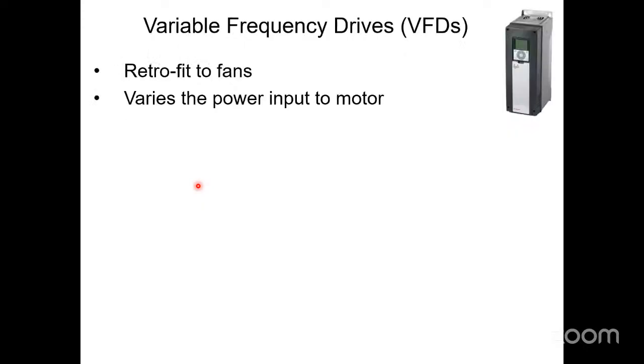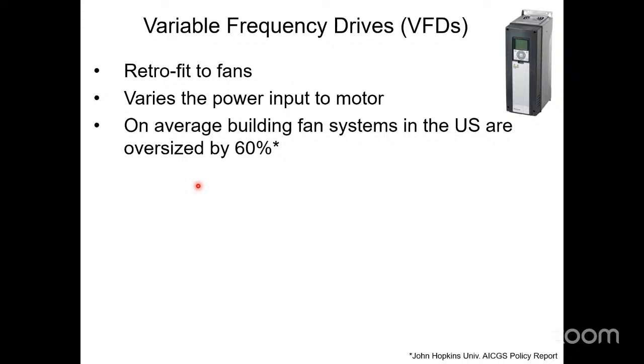The reason we use VFDs is VFDs save a bunch of energy compared to these other options. It varies the amount of power being sent over to the motor to begin with. If you didn't know, fan systems are pretty grossly oversized. So ramping them down is normal.